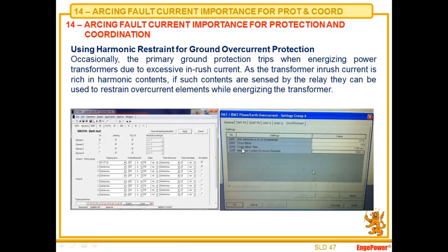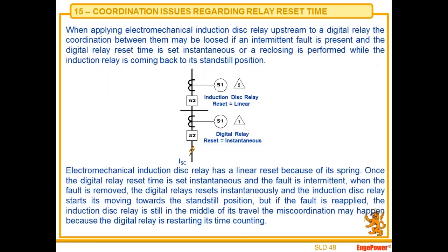So this is one manufacturer. Here's another one. These are the places where you can do this when you are setting your relays, providing harmonic restraint. Another issue is coordination issues regarding relay reset time.